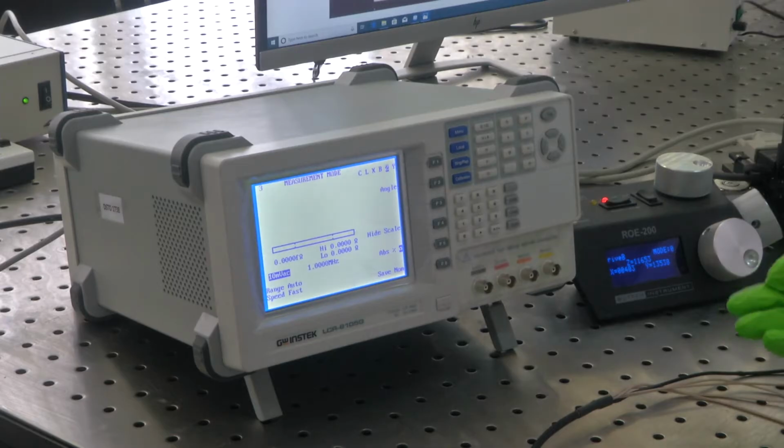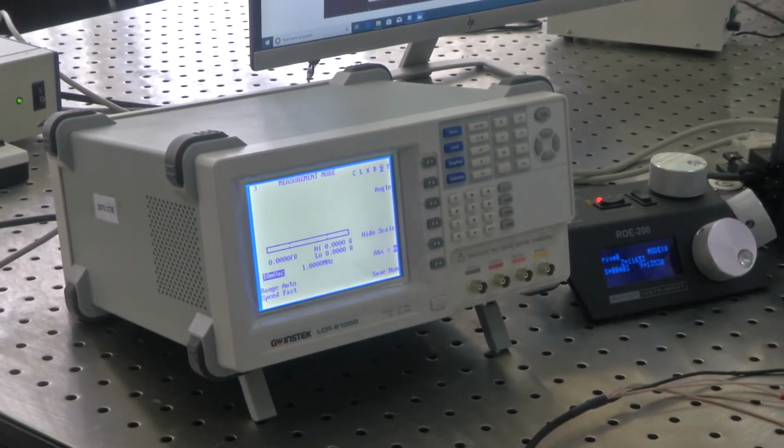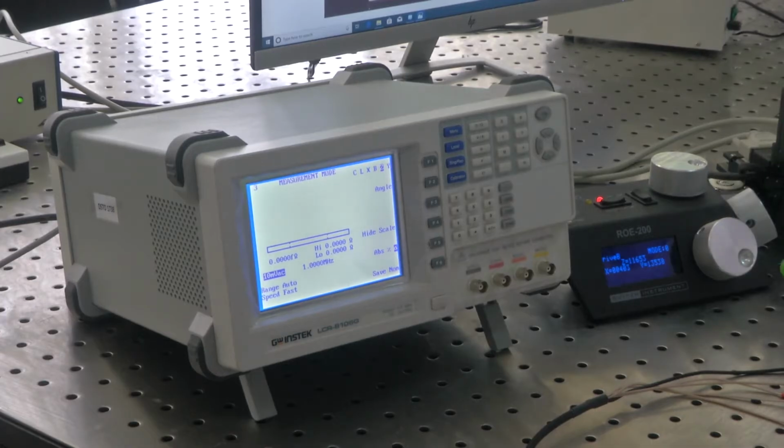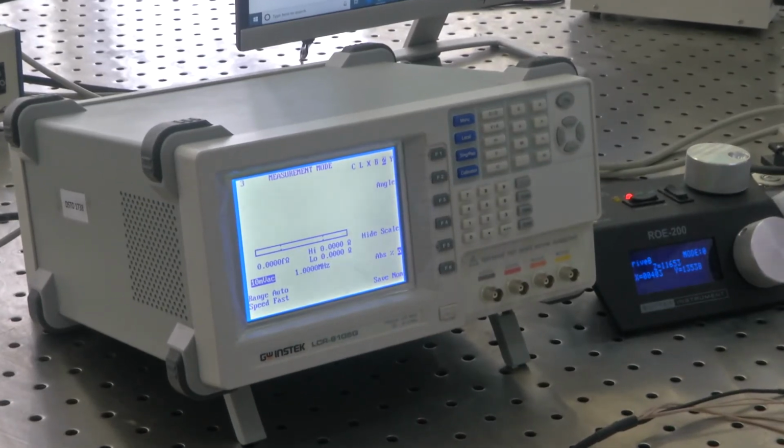Second, another important thing is the accuracy of the impedance value, or the absolute impedance, that we can measure with it. We are using these precise instruments that cost lakhs because we can measure the impedance very accurately, even to the range of ohms. The third parameter is the range of impedance values that we can measure with it, which can vary from 0 to a few mega ohms. And the fourth key specification is the phase value accuracy, or phase angle accuracy.